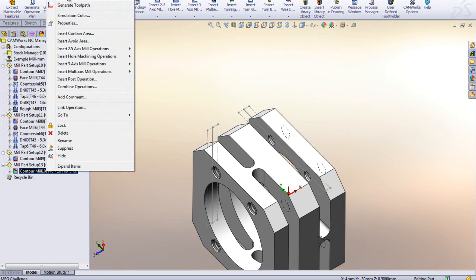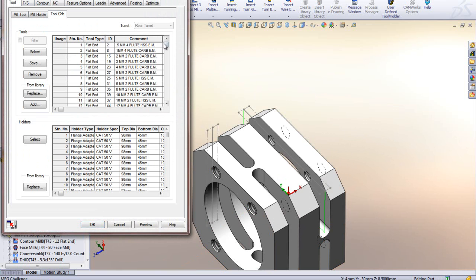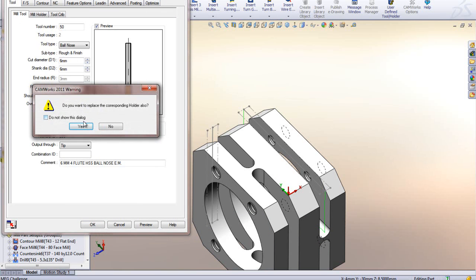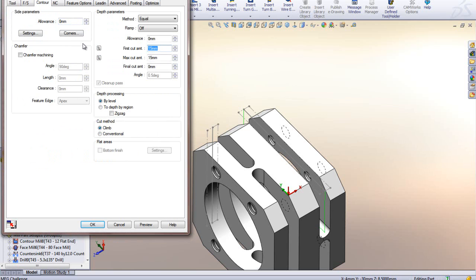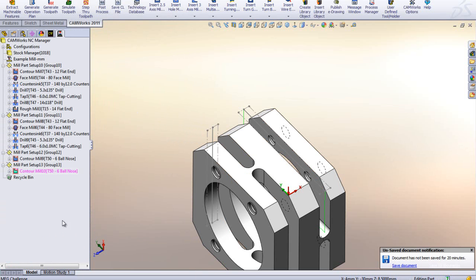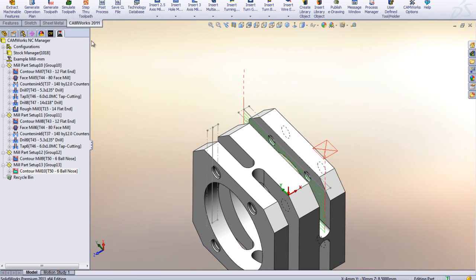And again, I just need to change the tool, but now I already got it, so I can just go into the tool crib and go all the way down to the bottom right and sitting right down here, select it there, take the tool holder with it, and we still got to turn off these here and maybe just change these depth here. So as you can see, yeah, we could do that in CAMWorks too, right? Pretty easily, not the biggest hurdle to do this.